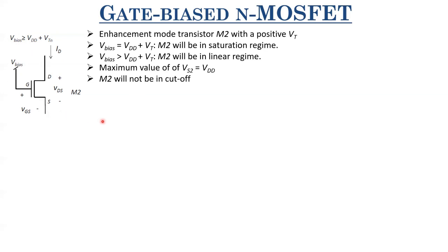And if you look at its output characteristics, ID versus VDS characteristics, you will find that it starts from 0 itself. I mean, there's no VT, it starts from 0 and not from VT. So it's away from cutoff even for VDS greater than 0.